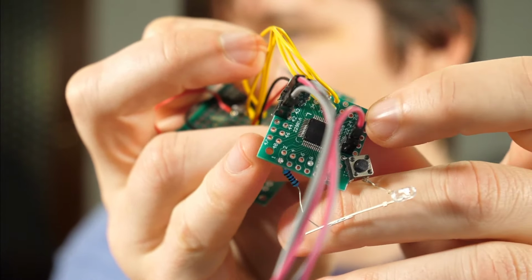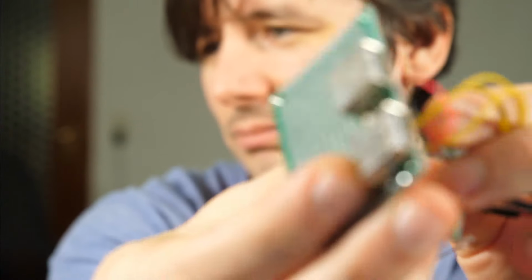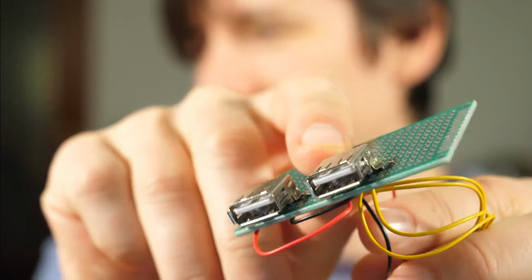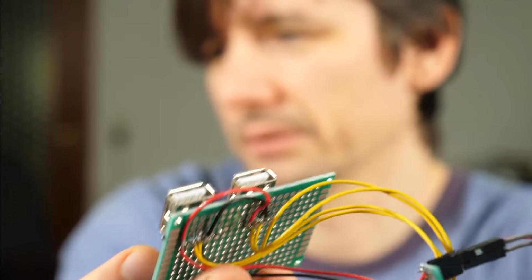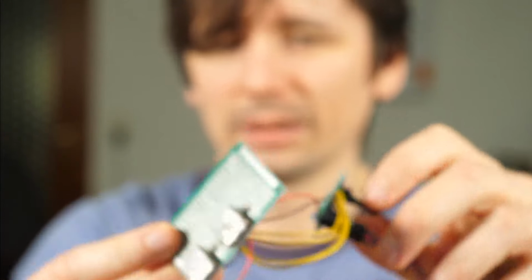I just soldered it on a breakout board and added a button and an LED to be able to program it, and soldered only the two USB connectors to it, and that actually worked. This is a serial converter, so I'll be able to see the debug output of this. So this is set up in an hour, and this is how I started. But nobody will do this at a hobby level. Nobody will try to do it, or maybe, and it is tedious.